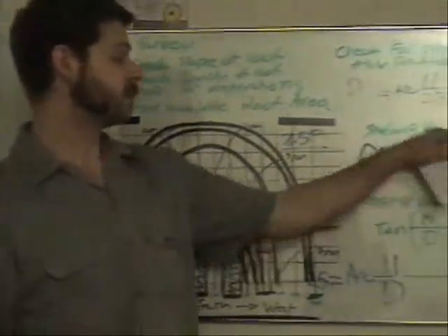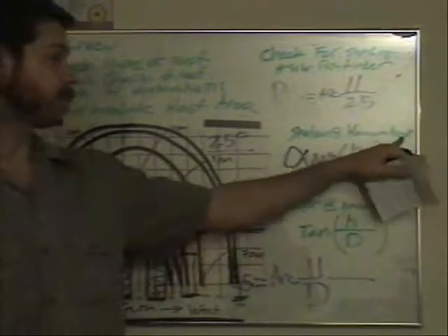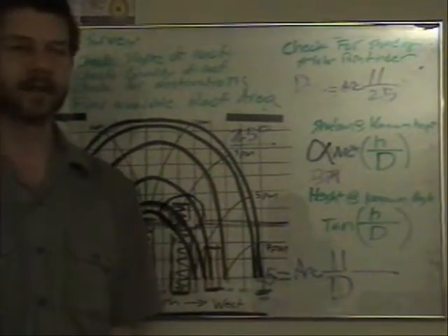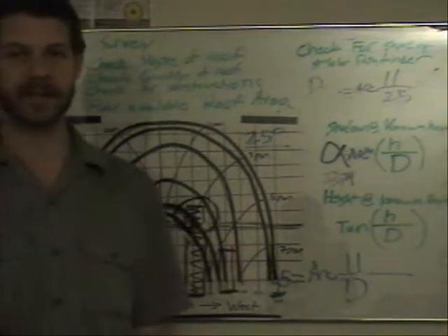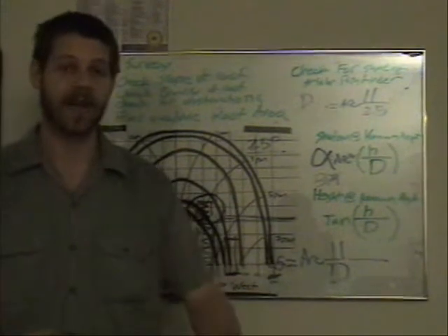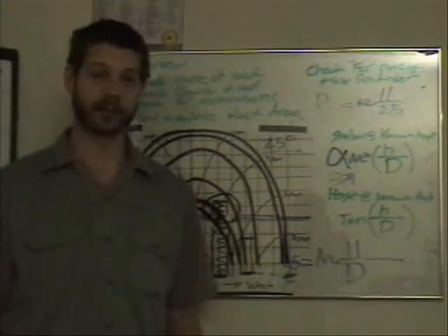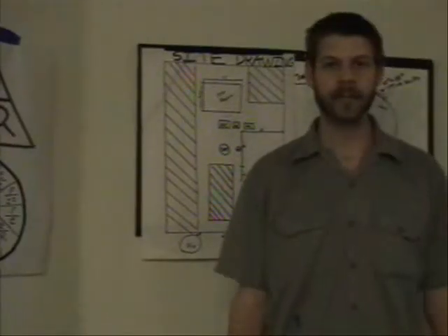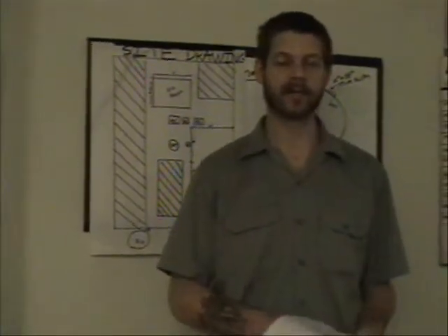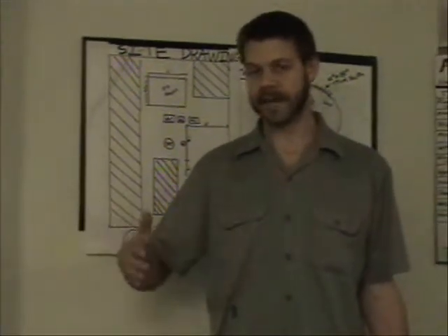This determining the shadow at a known height is good for obstructions that are easily measurable, something that's going to be easily in the way all the time, and to determine how far back from that object you have to put your solar array. Okay, so now that we've determined the shading on the area, and we've done our site analysis, we've looked